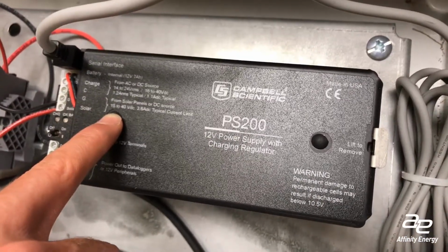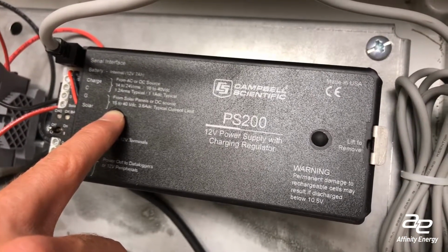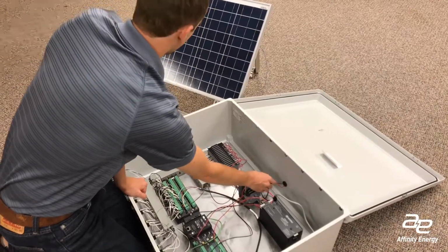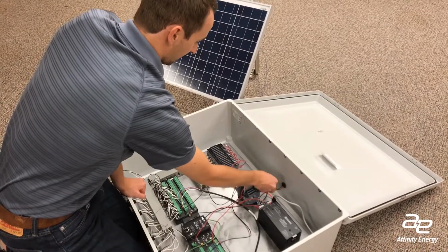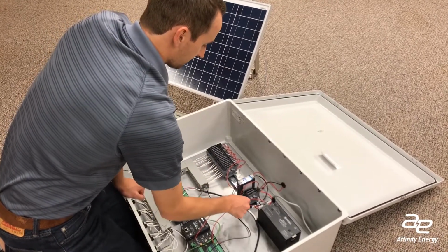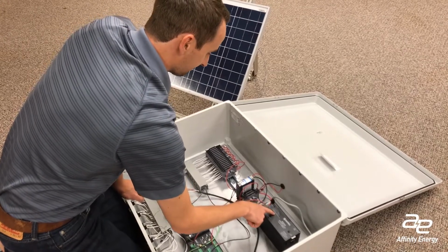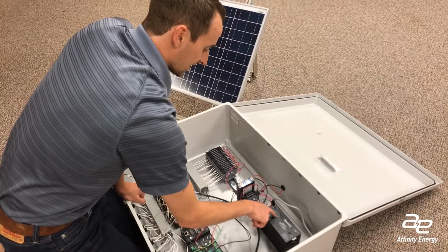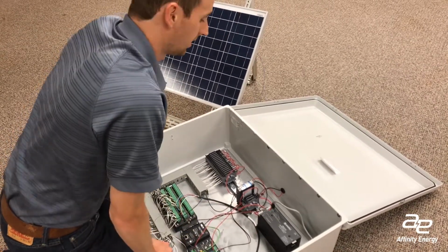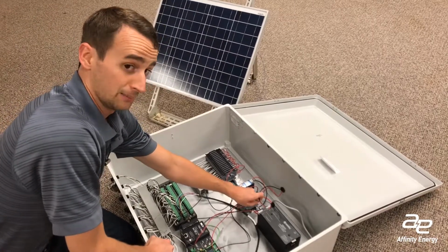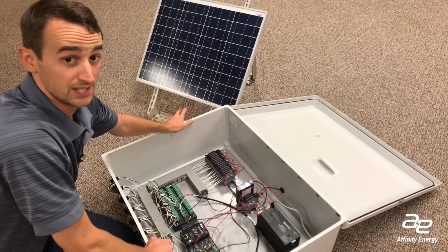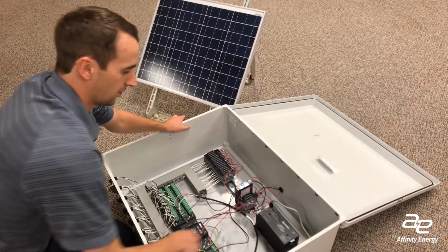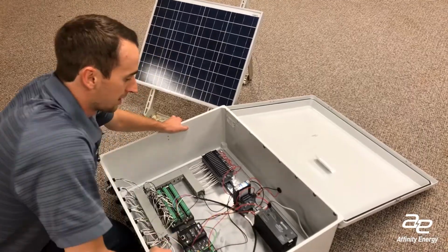The battery is a 12-volt battery because our devices are 12 volt. And so the output from the charge controller is 12 volts. And the input is from this solar panel here. And we've got the input coming through a fuse and then going into the charge controller. And it's rated for 15 to 40 volts DC at 3.6 amps DC typical current. Those are specifically the solar inputs. And so our panel is rated for 17.8 volts DC at, I think it's 2.8 amps. So that fits within our specifications.